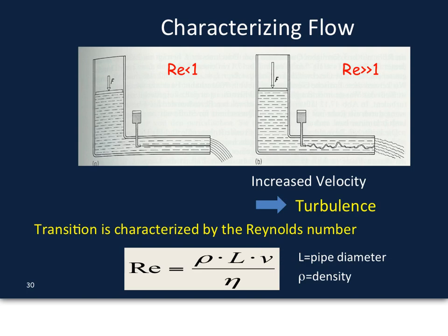And you can see that for a given size pipe and a given fluid, with a given density and viscosity, your Reynolds number is going to depend on this velocity, right? So if you have a much larger force pushing on the fluid, you get a much larger velocity, you can get much more turbulent flow, and so then you'll get a Reynolds number much greater than 1.